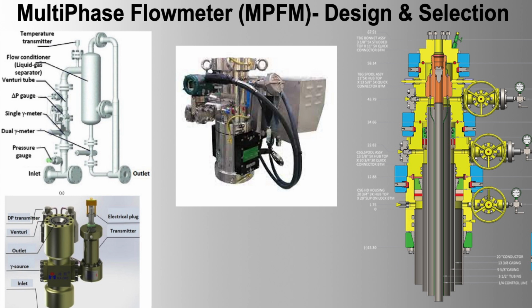Advantages of chemical injection at wells. 1. Precision in chemical dosing. Accurate phase measurement. MPFMs provide precise data on the oil, gas, and water fractions, allowing for more accurate dosing of chemicals, such as demulsifiers, scale inhibitors, and corrosion inhibitors. Targeted injection. By understanding the exact composition of the produced fluids, operators can target the injection of chemicals where they are most needed, improving their effectiveness.